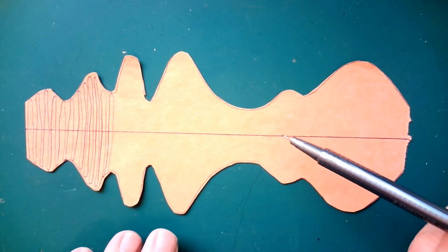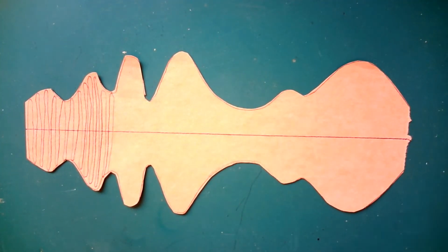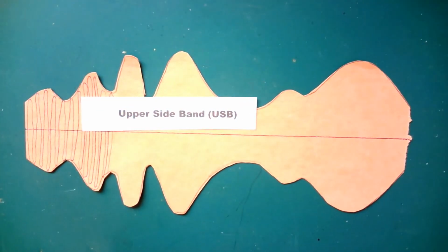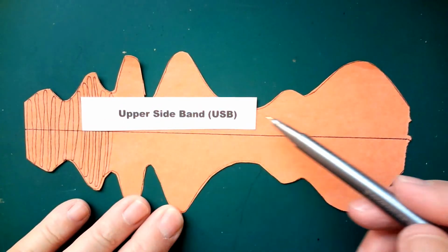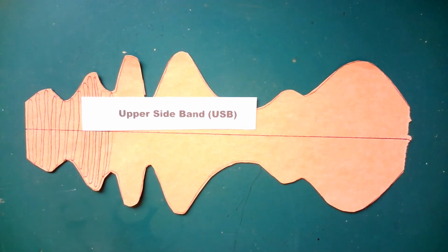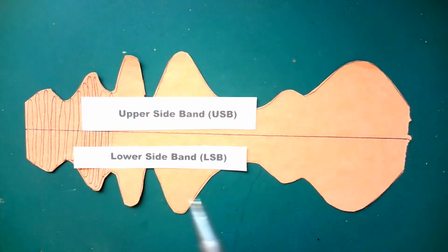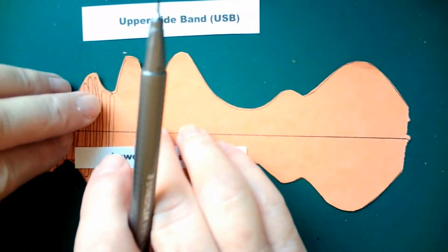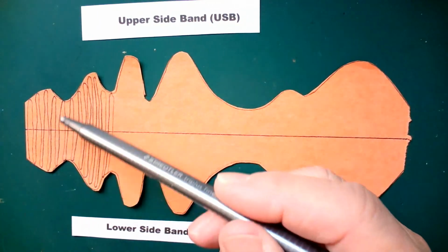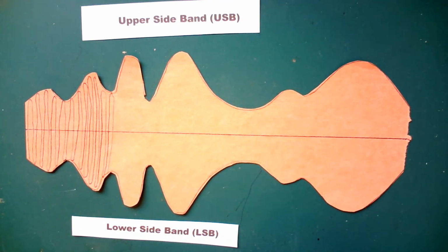And the radio wave has three parts to it. From the centre upwards, it's known as the upper sideband. So from the centre to the top of the amplitude at any one point, it forms the upper sideband. And as you may well suspect, the lower part of the amplitude modulated signal is known as the lower sideband. So there's the upper sideband and there's the lower sideband, and in the middle there is the carrier wave, which should go all the way down here, but I'm just too lazy to draw it out for you.